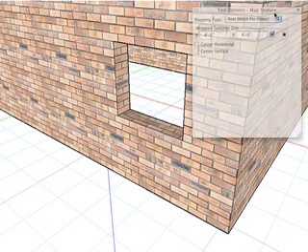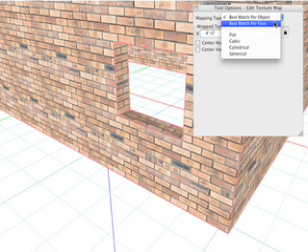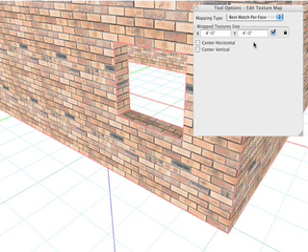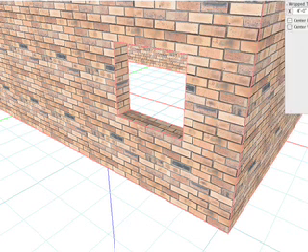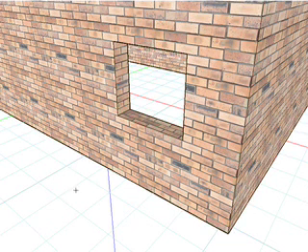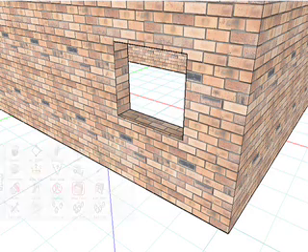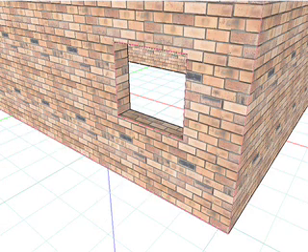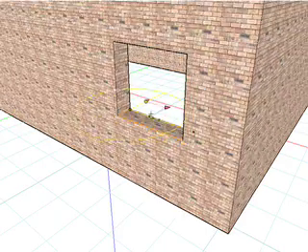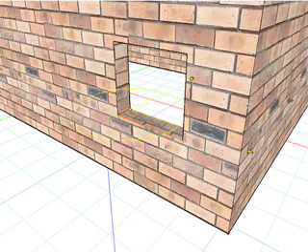In the Tool Options palette, we'll select Mapping Type Best Match Per Face. In addition, the Wrap Texture Size will determine the new texture size of the object. Click on the object, and all of the mapping is reassigned to all faces of the object, and they are regrouped as a single group of faces. To see this, we can use the Edit Texture tool, click on any face of the object, and you can see they are all grouped together as a single group of textured faces.